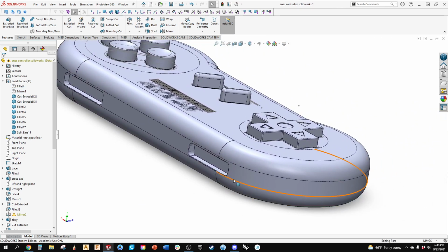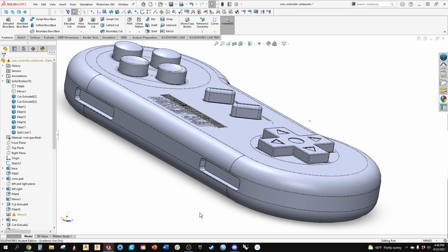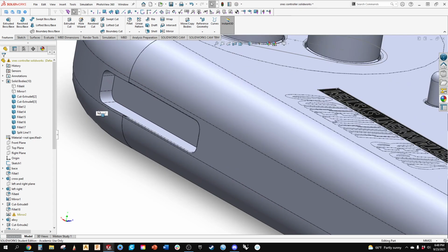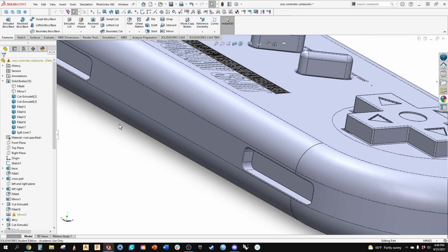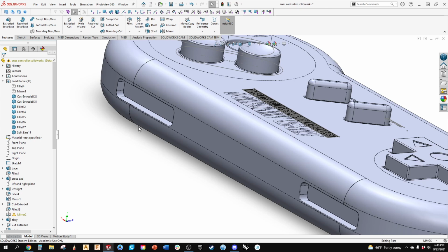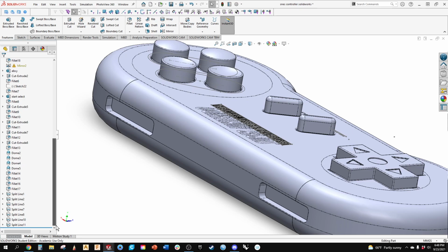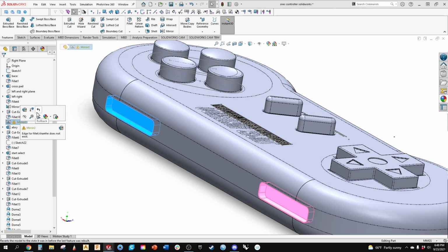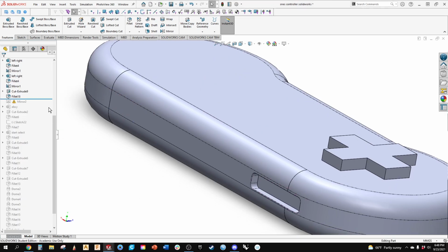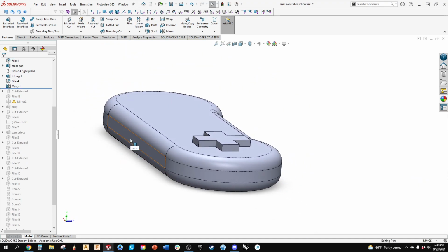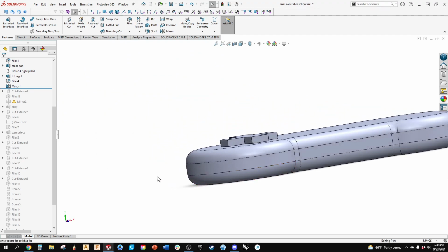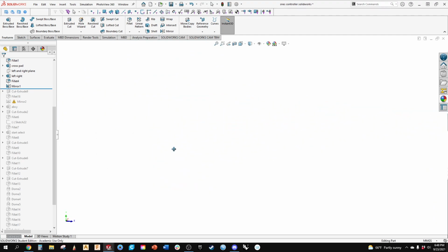So what you can do is do an extruded cut. Ooh, that fillet didn't mirror over, but I'll let you fix that. And actually, we're going to put that part line in prior, and I'll explain why here in a second. The reason I want to put that part line in now is because this is going to give me the chance to just do a cut extrude all the way around.